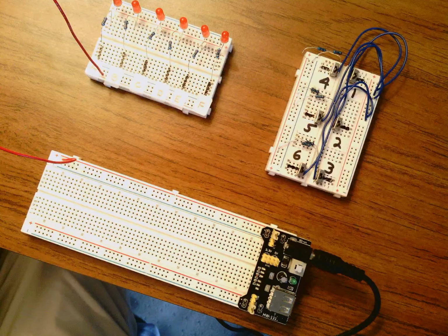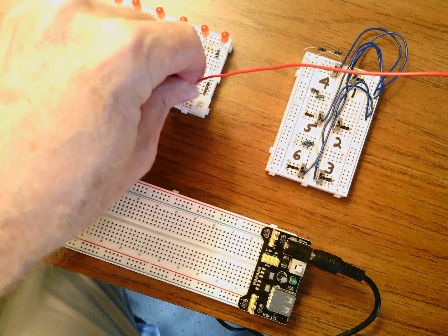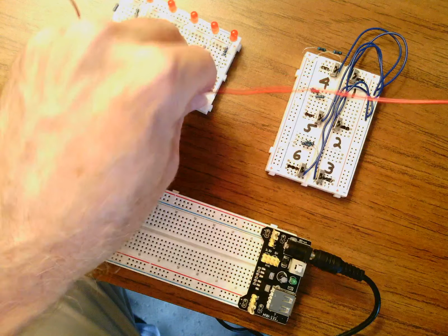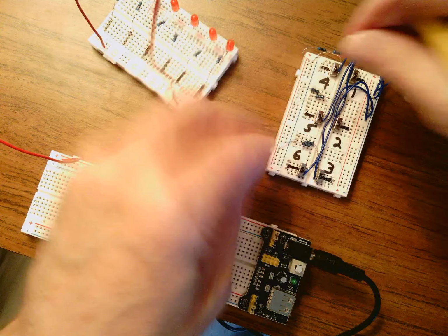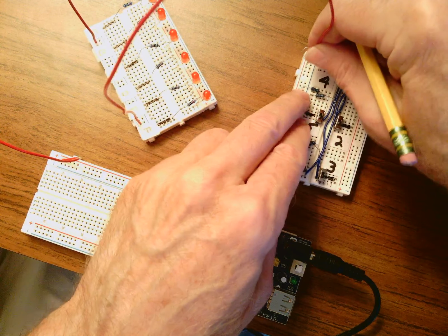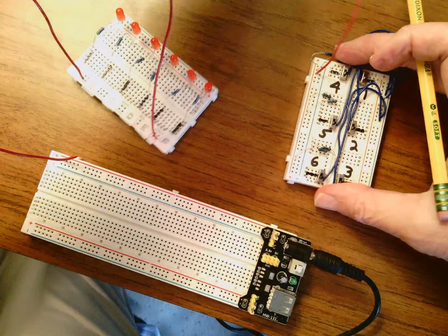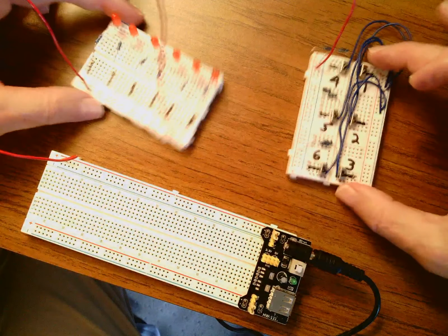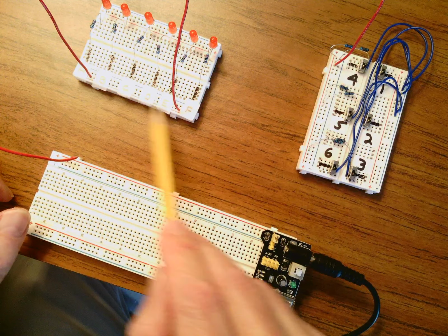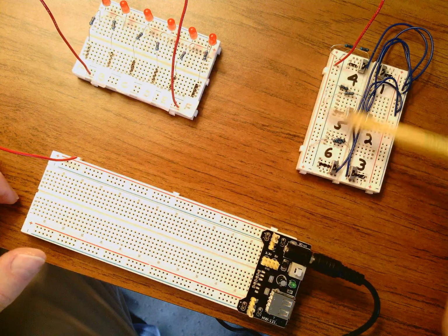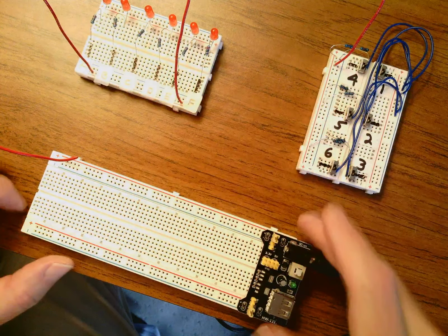And then I'm going to get another long red wire and continue the process. I'm going to take the rail here on the LED assembly and run it over to the red rail on my data assembly, my switch assembly that looks like that. And you can bend these around a little bit just to get them out of the way. So now when I turn this on, I have 5 volts here, 5 volts across here, and 5 volts the whole way down here, biasing up this rail and this rail and this rail. Now what about ground?